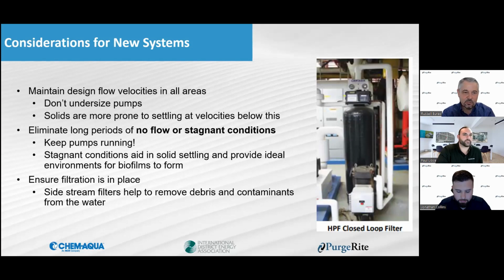And then, of course, not flushing and cleaning new buildings that are being attached to a larger system can create a big problem, because you'll insert those contaminants.